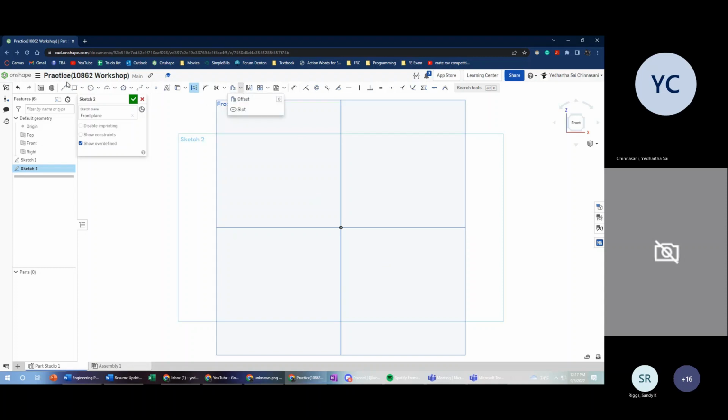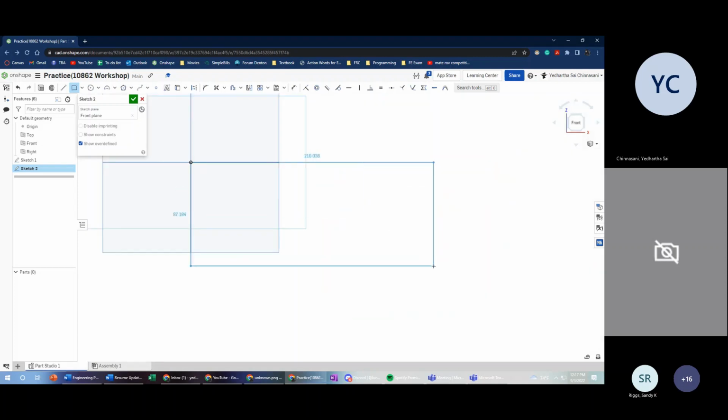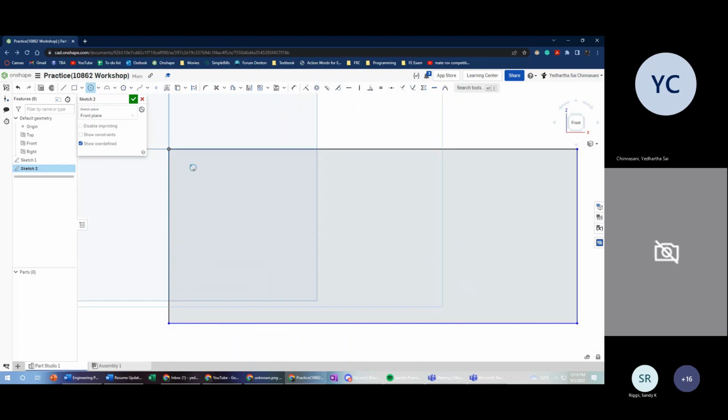So let's first get started. We just want a square, right? Let's just build a square. We have a bunch of holes that we want. We want a hole right here, a hole right here, and a hole right here, and we have 4 holes. We're trying to make these holes line up straight, and we're trying to make these holes the same diameter. So what you do is you click on dimension, which should be one of the options up there. As you can see, I press D on my keyboard, and the dimension tool will activate.